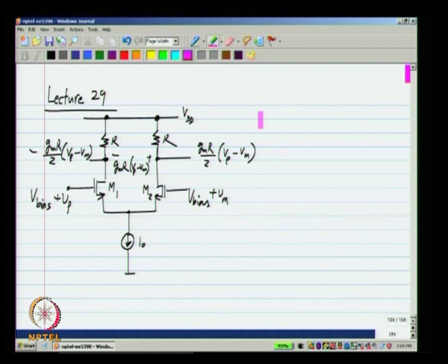In an op amp of course we want an integrating behavior. We would like this current to go into a capacitor. We will see how to arrange that. But for now we know that the currents through these are related to Gm times Vp minus Vm by 2. Now we also analyze the large signal behavior.